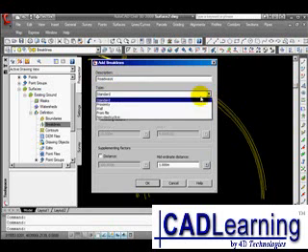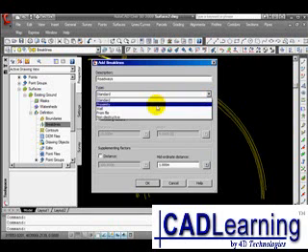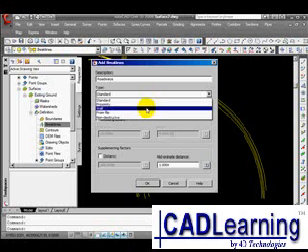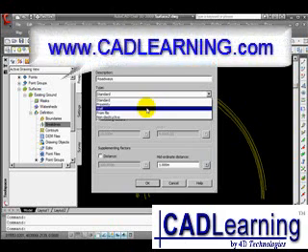There are 5 options. A standard break line is defined by selecting actual 3D lines, grading feature lines, or 3D polylines that represent break lines. A proximity break line is defined by a feature line or polyline where the object vertices are determined from the surface TIN points in closest proximity to the corresponding vertices of the break line. That's the type we want here. A brief overview of the other types. A wall break line is where you provide an offset side for a break line to represent something such as a wall and an elevation difference for each vertex along that break line.